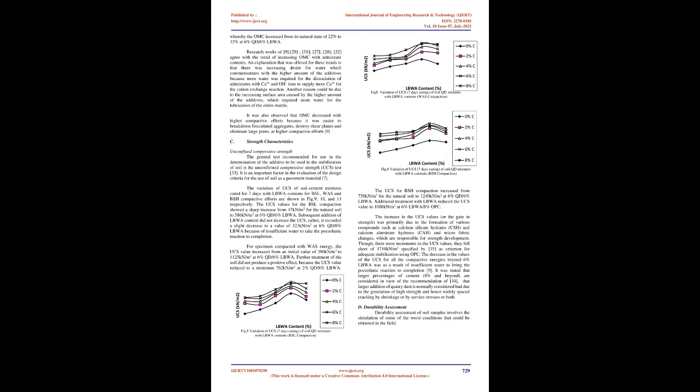It was also observed that OMC decreased with higher compactive efforts because it was easier to break down flocculated aggregates, destroy shear planes and eliminate large pores at higher compactive efforts.